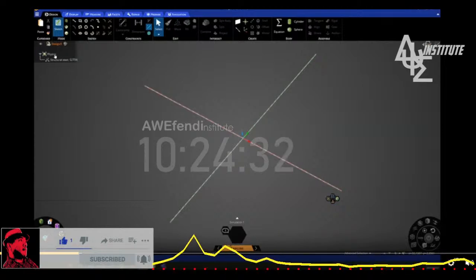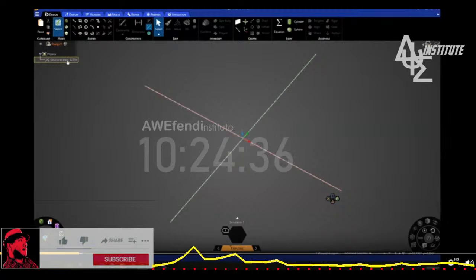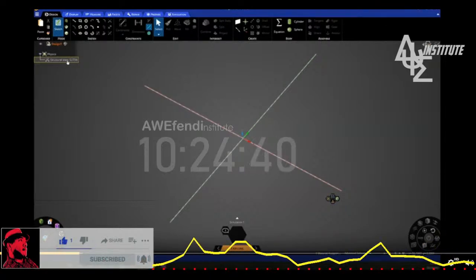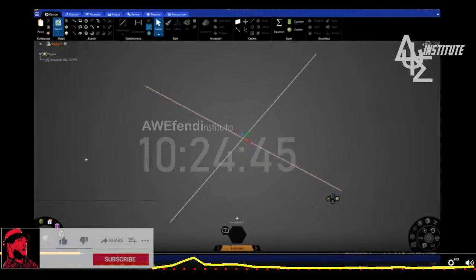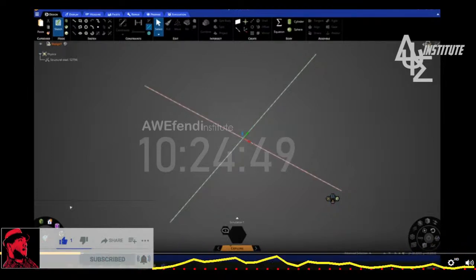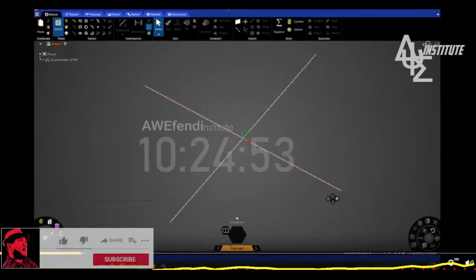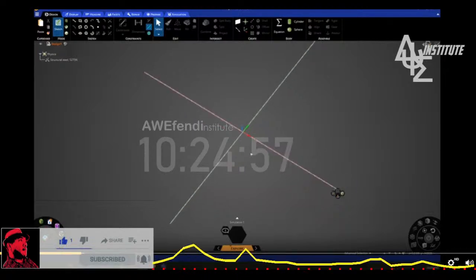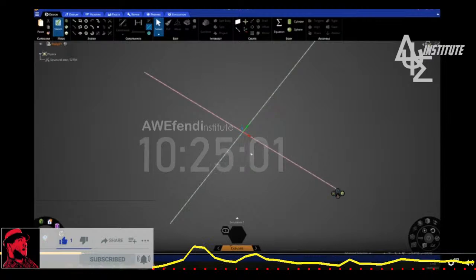The next is the physics tree, where you will see the material of the model that you're going to be using, as well as the boundary conditions. Over here, you see structural steel, which is defined as the default, but you can feel free to change that in our settings. And the third important area during modeling is the one over here. It's called the viewing arc. This is used to change the view of the model or how the model looks like. If you want to see it in a wired form, you want to see a shadow model, whatever you like.